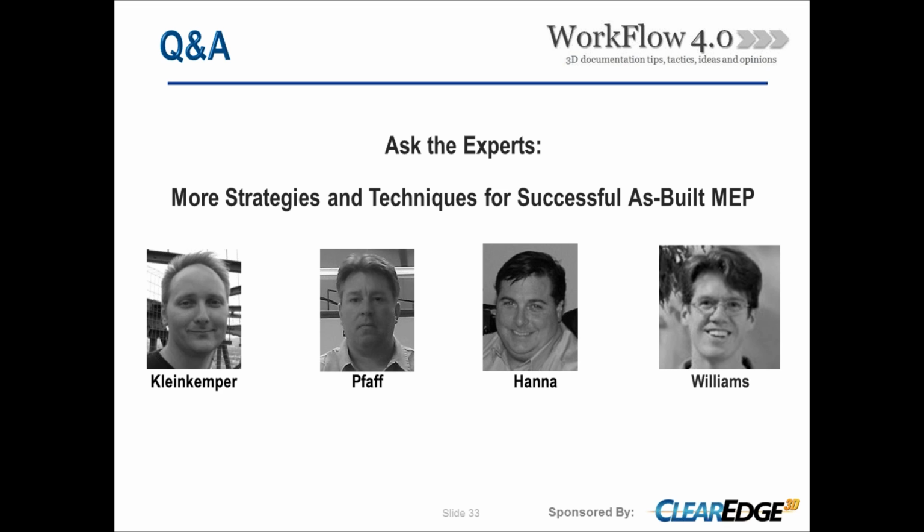Mark, this question is for you specifically. When you're using a C10 and a Faro Focus to do the hospital, what software do you use to complete your registration with the two different scan data? Well, we typically stay within the scanner software. So for the Faro, we're using Scene to do our registrations, and for the C10, we use Cyclone.